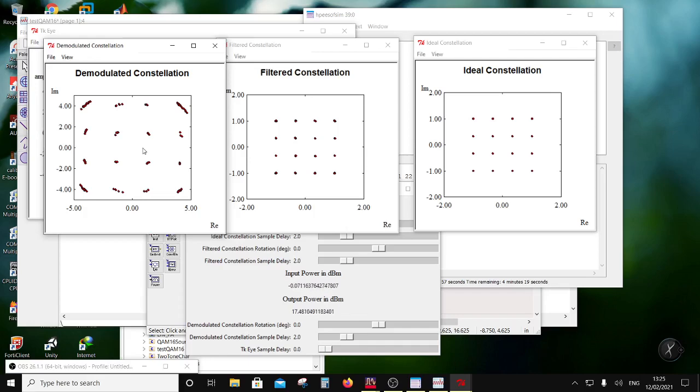And whatever EVM I find out here is not just from the PA, right? That error vector RMS would also have a contribution of the phase noise, right? So what we are testing here is the PA. So I will put the phase noise to 0, and then measure the EVM of the PA. But in a system, you will see that the RMS EVM is going to change because of the phase noise of the PLL, right? And this phase noise is not statistically predictable.